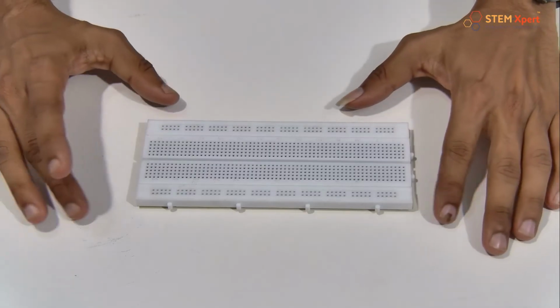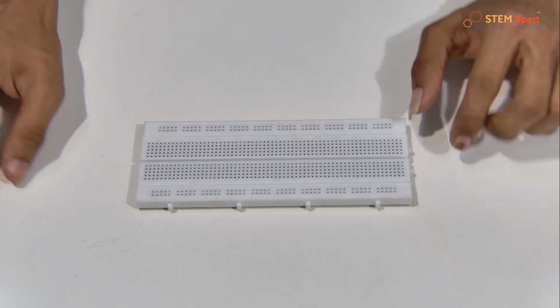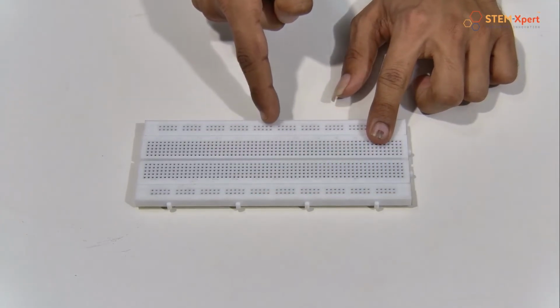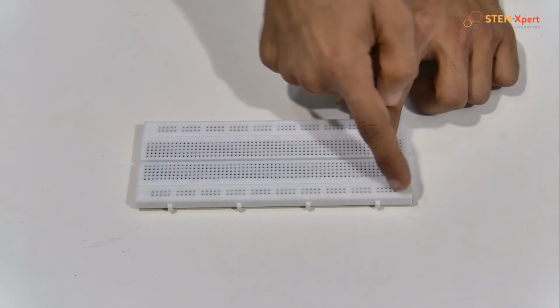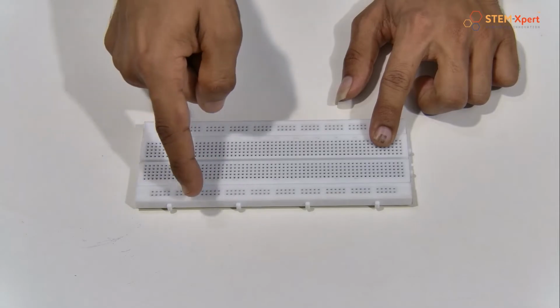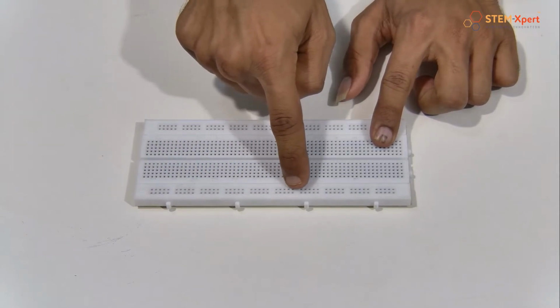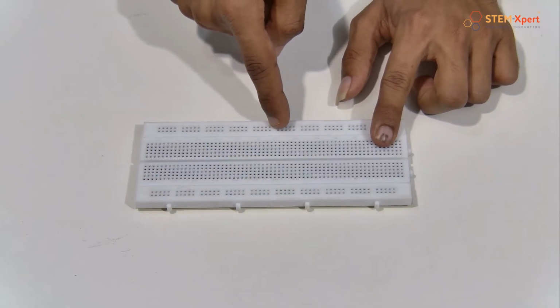So in this session, we are using a big breadboard. That means it combines 5 plus 5, 10 sections. 1, 2, 3, 4, 5. So this is a small part of the breadboard in which points 1 to 5 are interconnected. Not in the case of 5 to 10. That means the 6th point of this breadboard is not interconnected with the 5th point. Here the connection is closed. I hope you have understood.